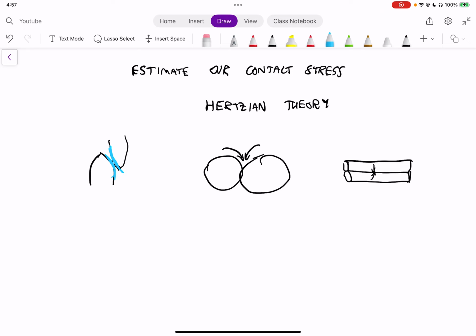The only thing that's required of you is really to understand how to apply this to a problem rather than know the whole derivation. So I'm going to write a few equations down. I'm going to write the dictating equation: P max, so pressure max, is equal to 2F over pi BL. And I'll define all of these terms right now. P max is going to be the largest surface pressure.